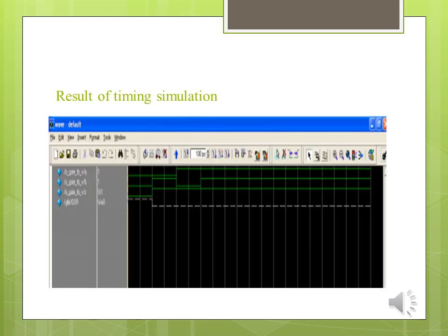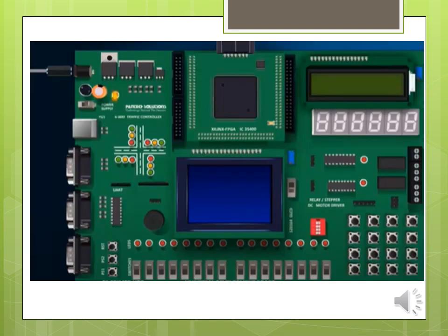The performance calculation and design verification can be done by using an interface to a timing simulation program such as ModelSim. Performance calculation and design verification can also be done by downloading the configuration bits into the FPGA and checking the part within its circuit board.